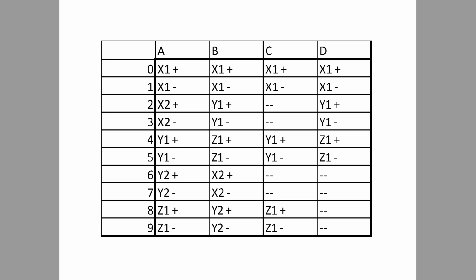As we've seen, there are quite a few different ways we can put together the table ID numbers to what the function is using the CEC tables. These are some examples where I've got tables 0 through 9 with 4 representative machines A, B, C, D. So if we look at A, we're going to assume that A is a gantry, and the builder has decided that this is their standard, that they're going to keep X1 and X2 paired up near the top, Y1 and Y2 following, and then followed by Z1. If they decide that this is their standard across their entire product line, when they make a machine that's not a gantry, they may just go to column C and outright skip tables 2 and 3 and just not use them. That's completely and totally fine because that matches their standard.